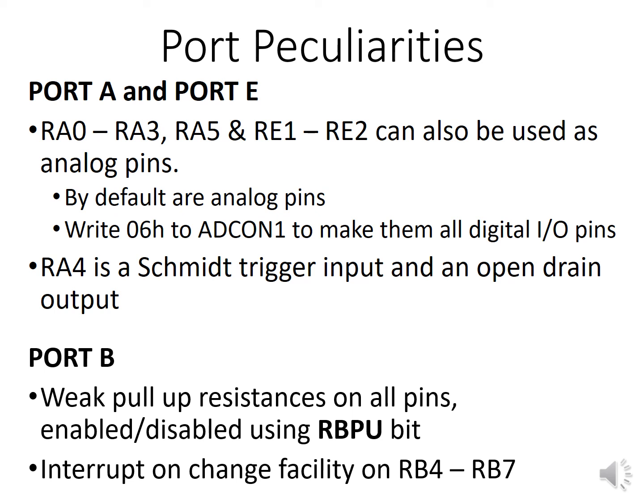pull-up resistances. Also on port B, there is an interrupt-on-change facility on pins RB4 to RB7. This means that whenever any of those pins changes state, an interrupt is going to be raised. So also, you may consider some suitable uses for this kind of interrupt.